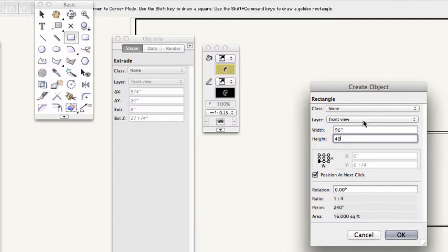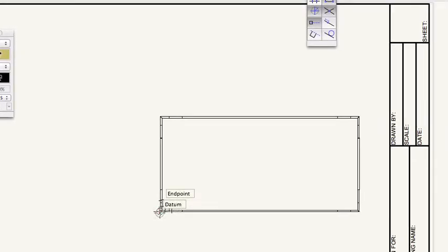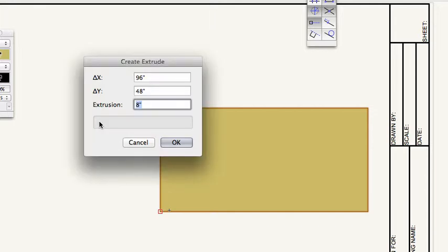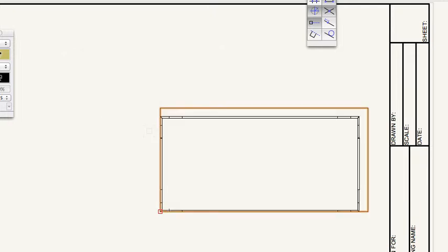And I am going to go ahead and use that same insertion point, and I'm going to put it right there and click. I'm going to extrude it so that I can see it. We know the tabletop is 3/4 of an inch in height, but it's not properly located, is it? We want that 2-inch margin all the way around.